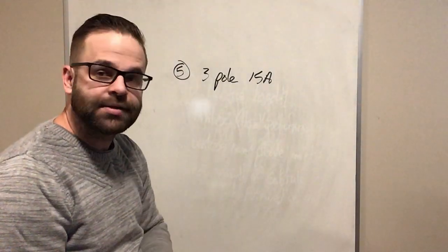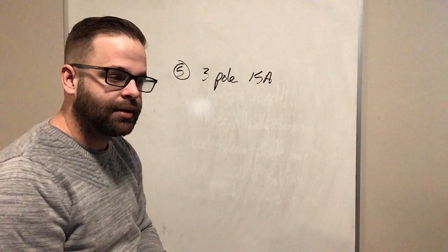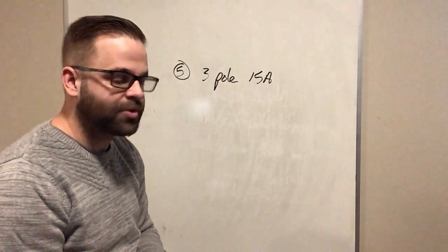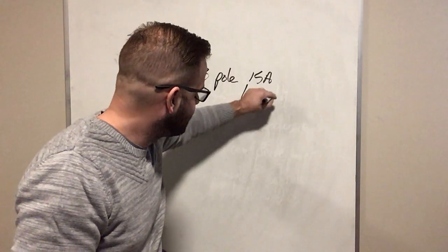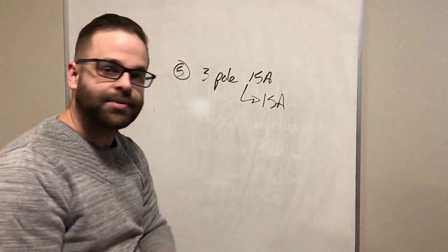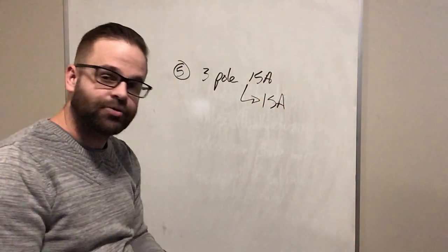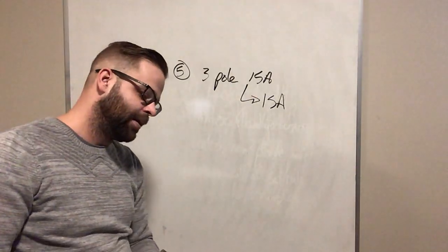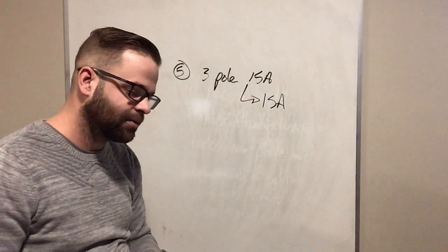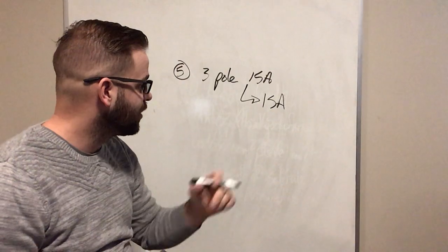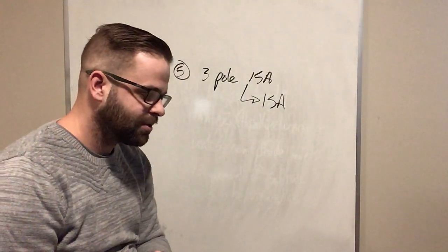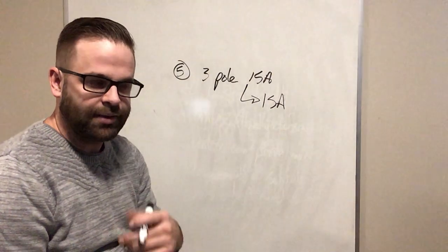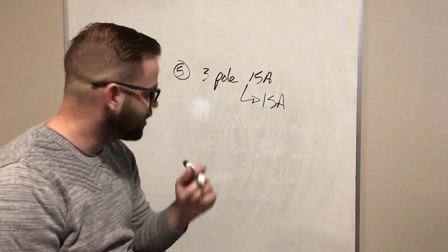There are some cases where breakers can run at 100% of their rating, so this breaker would run at 15 amps without tripping. They're extremely expensive, but sometimes in certain applications, maybe certain hazardous locations, you need a breaker that runs at full capacity, continuous duty.